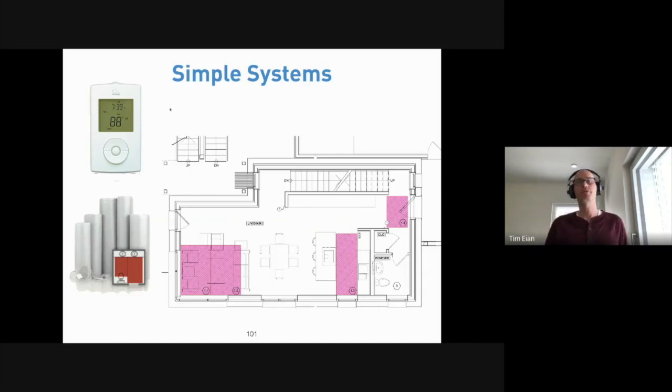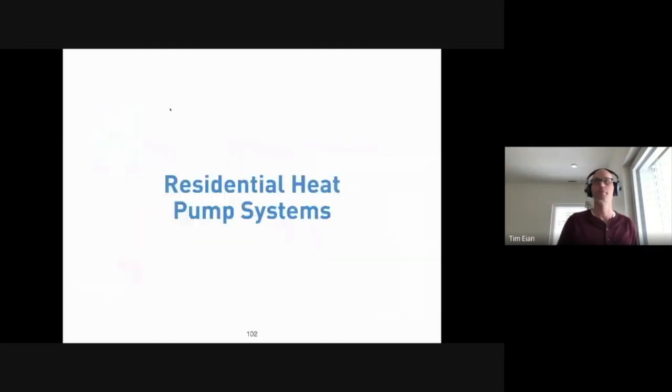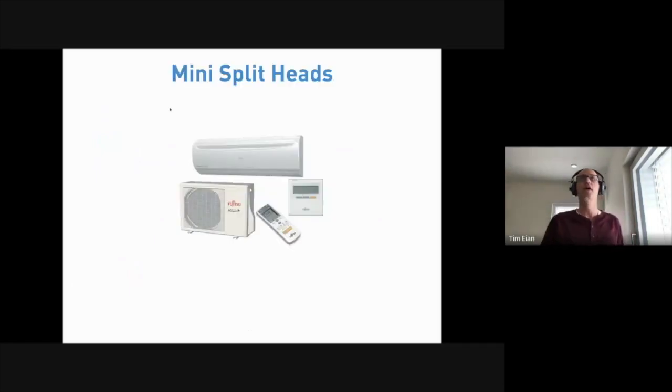We've done this with simple systems. These are in-floor electric heating mats. Our first passive house has that. You're not covering even the entire floor area. You're covering just, like, area rugs, certain parts that you want to experience that warmth in. And I always have to remind people, this system is 100% oversized for recovery time. So in reality, we could have gotten away with half the amount of mats on that floor.